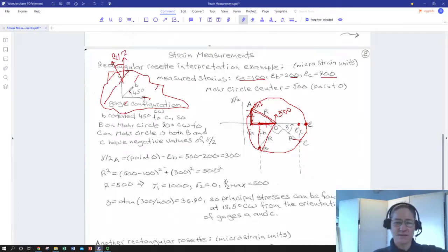It elongates. So if we have a bearing or a clearance or something we have to respect and we have some loads applied and we're worried, oh, where's it going to hit the side of a sleeve or a bearing? That's a good place to be looking. If it's going to impinge anywhere, it would impinge there because it's stretching the most in that direction. And likewise, if we had an O-ring that we had to make sure was staying compressed, that's absolutely essential for sealing, to make sure that you have enough squeeze, enough normal strain across the diameter of the O-ring.